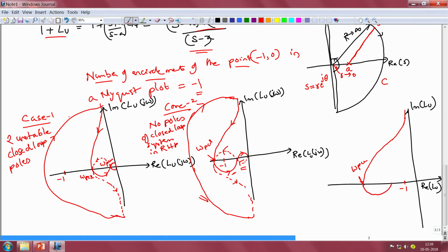and then subsequently it will cross over once again. So, the phase will once again assume a value of -pi at omega PC upper. So, this is omega PC upper, and this point is also a point that is to the left of the point -1, because in this particular case the gain of the open loop system would be greater than 0 dB even at omega PC upper, and subsequently the loop gain does its particular thing depending on the higher order dynamics of the plant and the controller, and finally goes to 0. So, this is how the Nyquist plot will look for the positive imaginary axis.